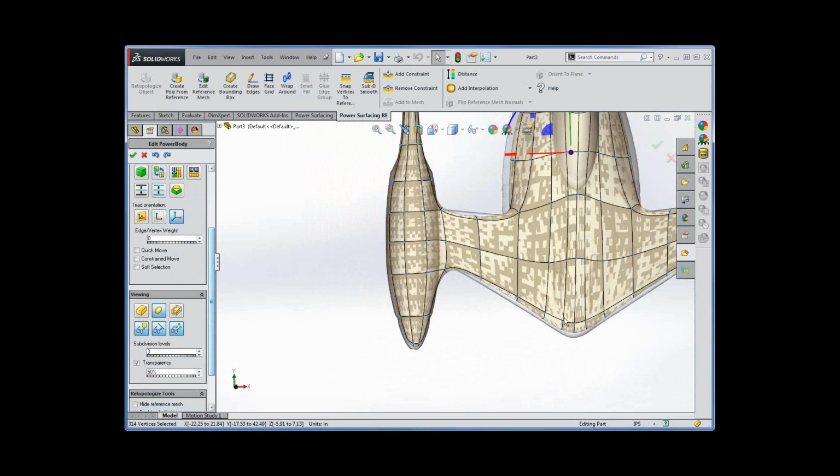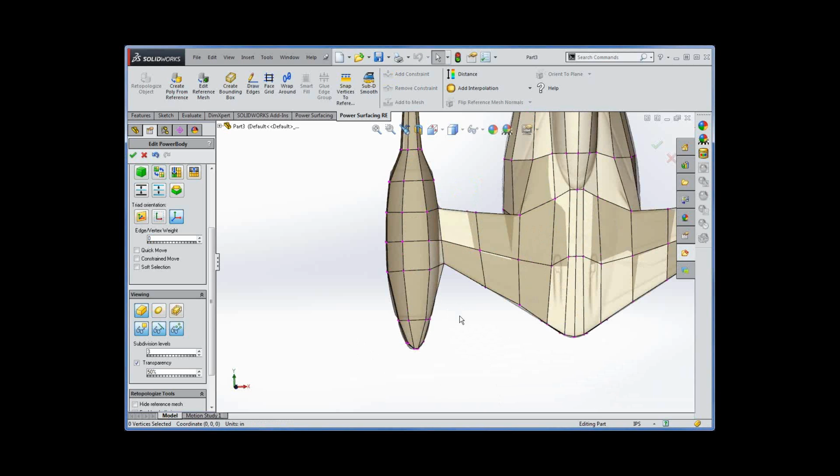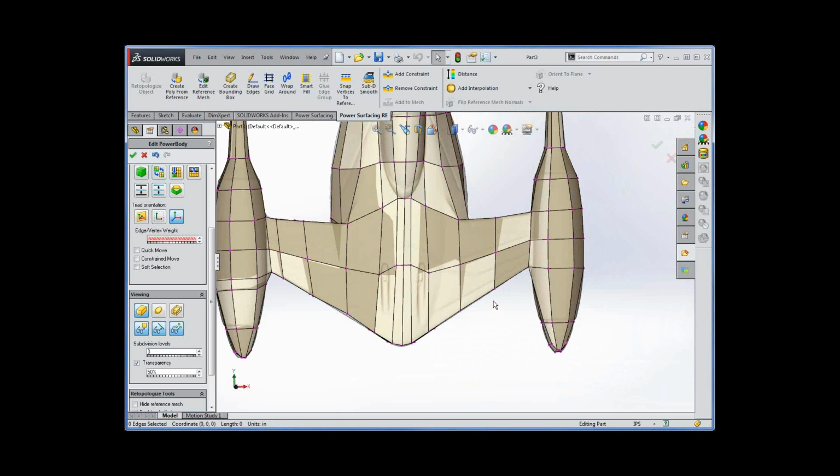And right now it leaves it in sub-D, so it's looking sucked in. By the way, that's one of the options, is you could model in sub-D and just match the mesh as a sub-D. That way you wouldn't have to use interpolate. You wouldn't get quite the accuracy, but sometimes it'll give you a lot easier ways to do more manipulation and modifications. But this time, though, what I want to do is I'll switch back over to control mesh, and in edge mode, if I hold my A key down, I can add edges, and I'll do that on the other side as well.